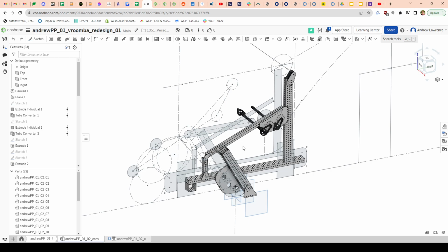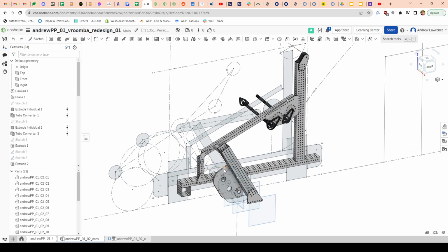So if I were to copy a sketch over from the main sketch folder and then paste it into here and then go back and change the original sketch, I am not going to have those changes reflected in the new part studio, and that's bad because then we're going back and forth changing sketches and eliminating a lot of the advantage.